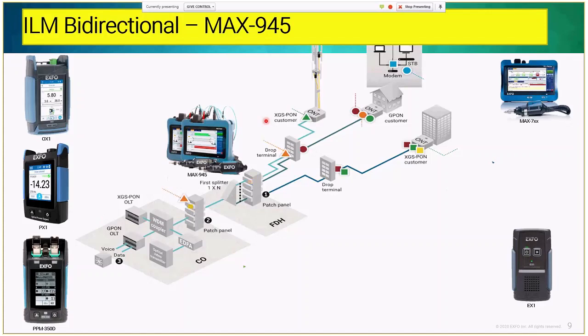What's the problem on this equipment? The problem when you use an insertion loss measurement test set is that it will not locate the fault. If you have a break on the link, it will just tell you that you don't have power, but you will always need to use a radar or an OTDR to find out where the problem comes from and to get it repaired.